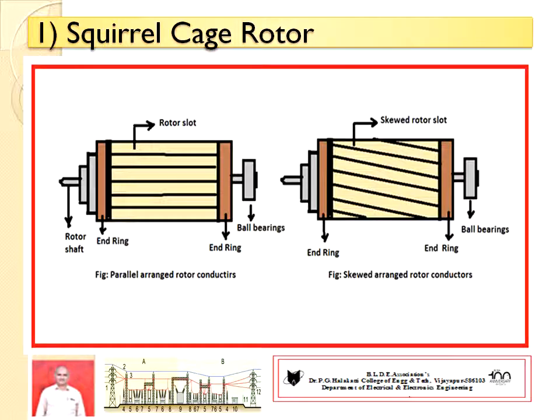It is already observed the rotor is a cylindrical drum. The rotor slots are punched on the outer periphery of the rotor core. The rotor slots house the rotor windings. The induced current in the rotor winding is very high. Therefore, instead of circular conductor, we are using bars, copper bars or aluminum bars instead of winding, that is a ribbon type of conductor. These are referred to as rotor bars or aluminum bars. These rotor bars have been placed in rotor slots. You can observe in figure number 1 parallel sided rotor slot which houses the rotor conductor, that is rotor bars.